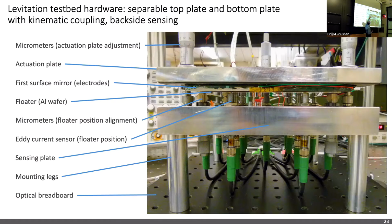So there are 3 micrometers with balls at the end with grooves. And therefore, if I want to make any change, I can just pry open the top surface and then put it back together within a few microns. The system is repeatable.